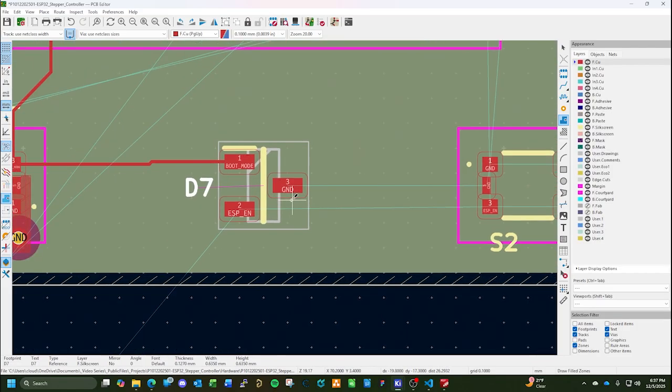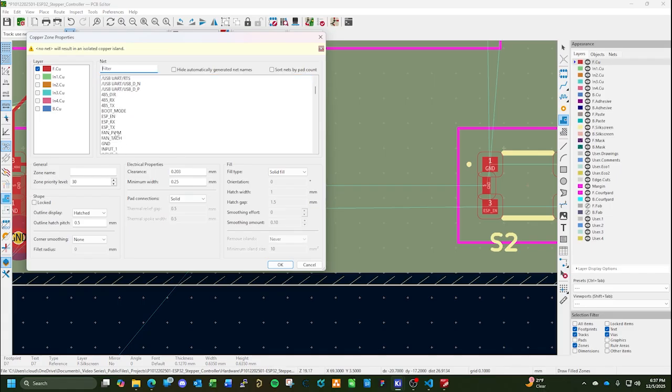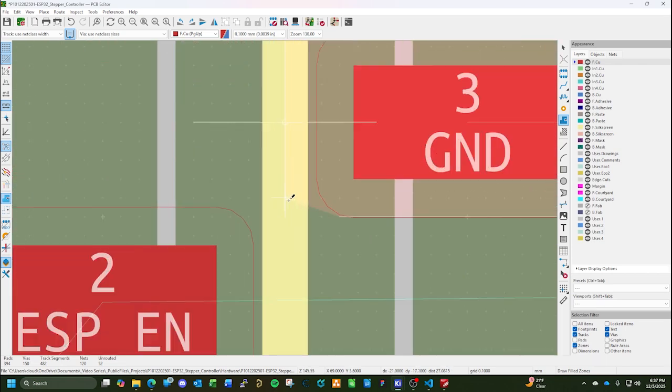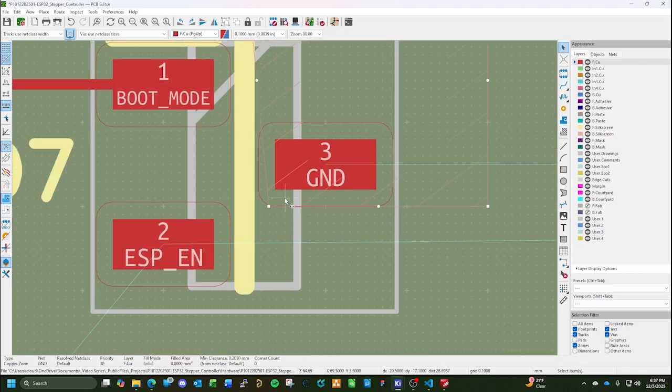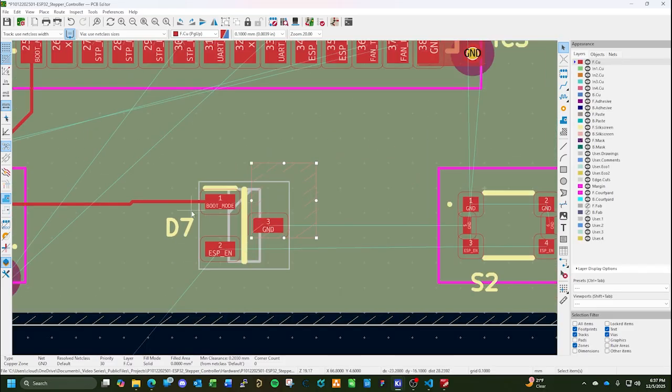So since this protects this, we're going to definitely make sure we put a good solid ground plane in. We want to make sure that we sink any of this extra voltage down to the ground plane. So we're going to just start by drawing our polygon. We'll fix it as necessary, but snapping to the grid gets annoying. So we're going to grab that. I didn't double click.